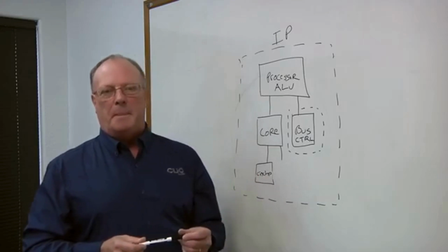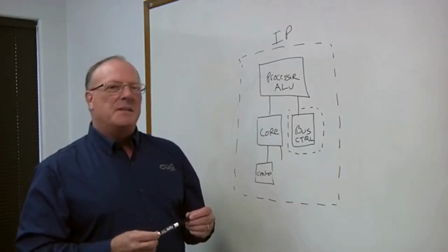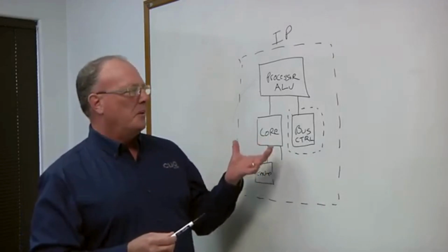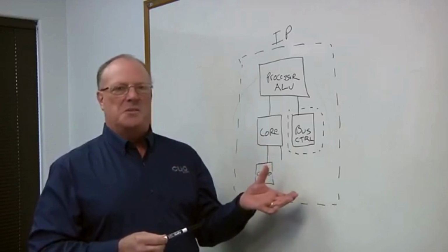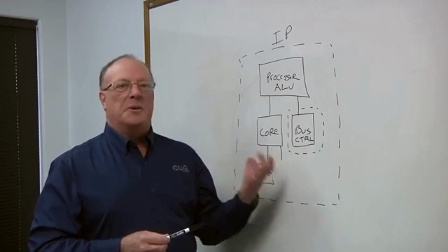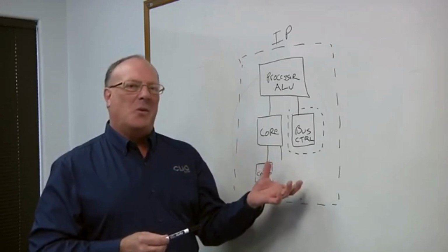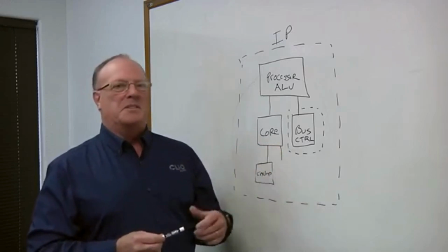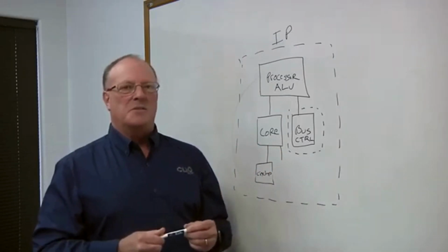So where do problems typically crop up? Usually in detailed validation. Most of the time the design teams are pretty good about finding defects, but when you actually put the thing into a system, you'll find unanticipated usages, or some of the constraints that you assumed at the beginning aren't true when you actually put it into the system. And so you may find that your tests are not quite adequate, or that you haven't fully accounted for a situation that gets into the field. So usually it's unanticipated usage.